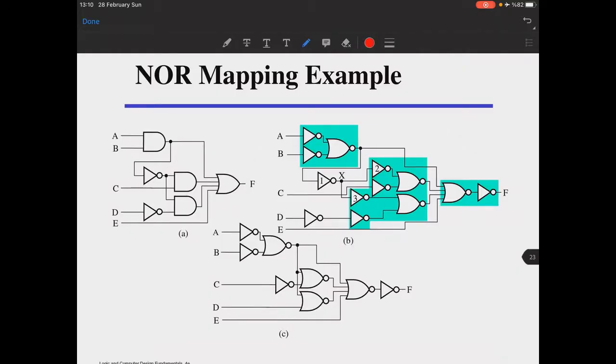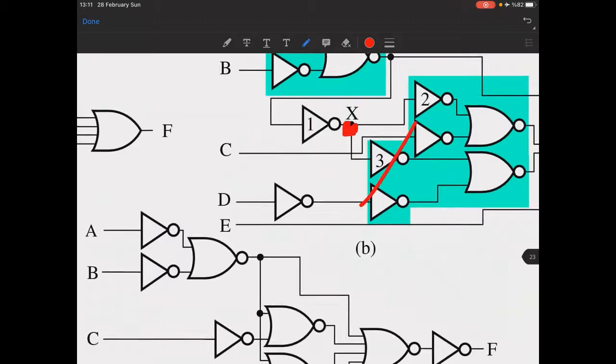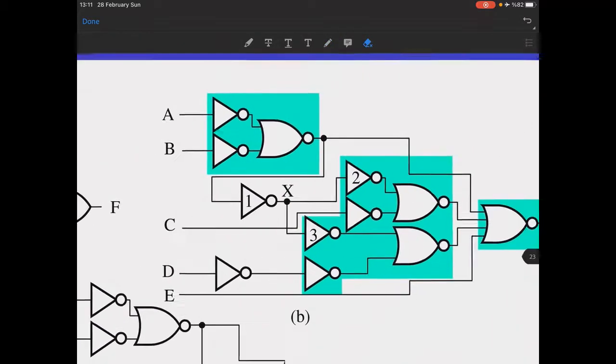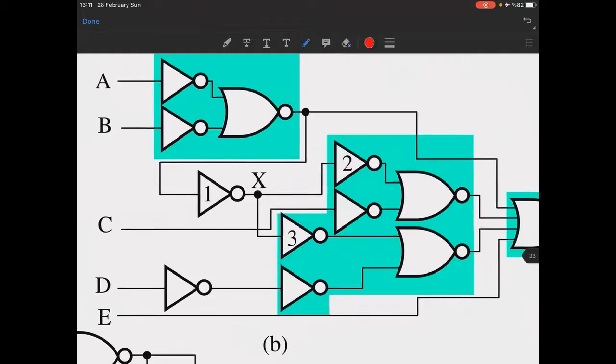And in the end, we have this. Let's look at what we can cancel here. Look at this. Okay. This one is a crucial one. Look at this particular fan-out point here. See? The fan-out point here is this part. Okay, we iterate this inverter to here, and this will be gone, and of course these will be gone and these will be gone. Great, so good.